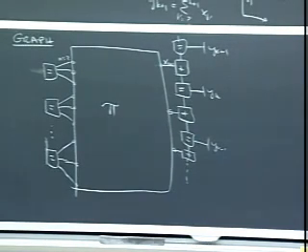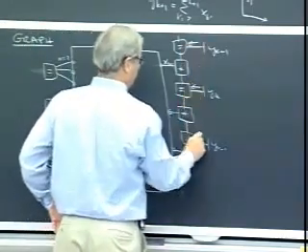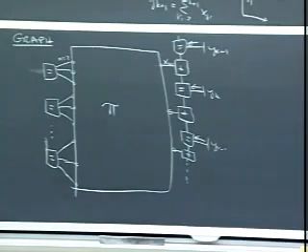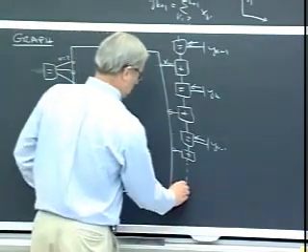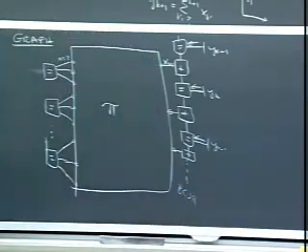So how would you decode this code now? What do we see initially? We initially get received data, measured intrinsic information for each of the bits that we actually send over the channel. And what's our next step? Trellis, yeah. We do the sum product algorithm on this trellis. So we just do BCJR, ignoring the fact that it's rate 1. Doesn't matter.